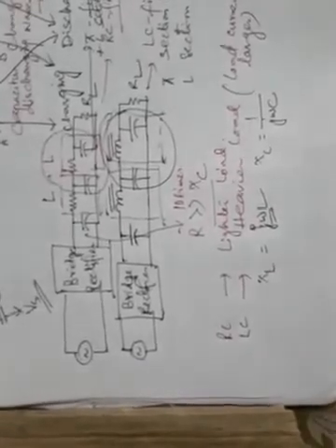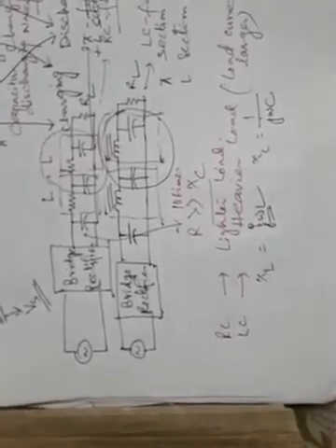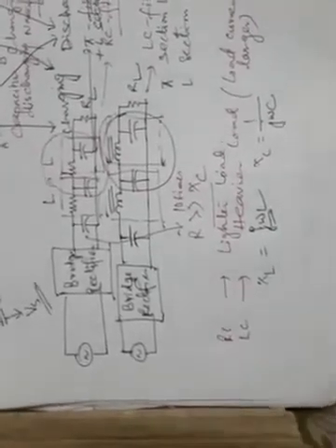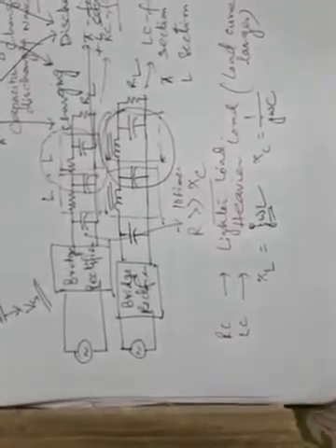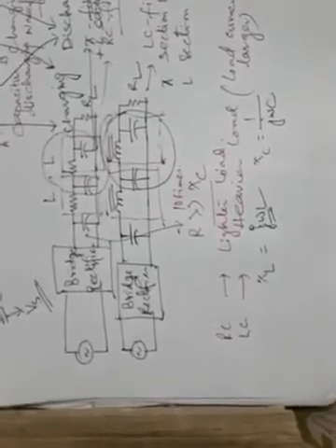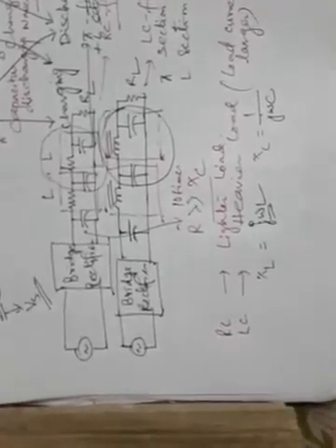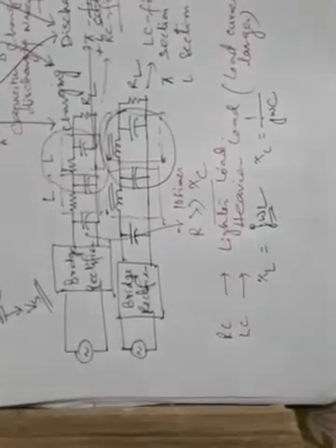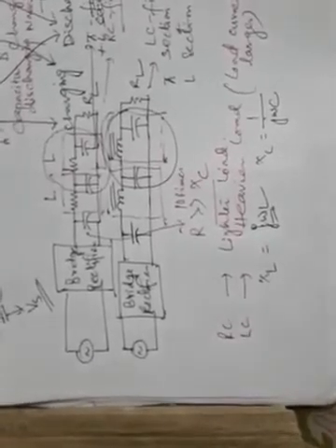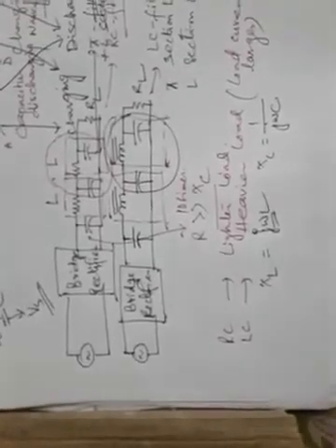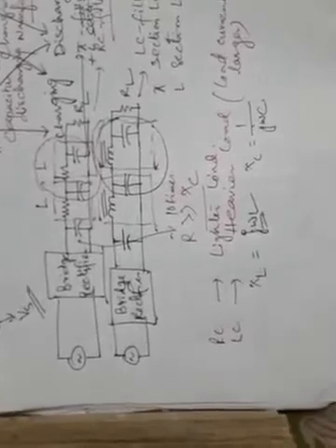So we can in this way reduce the ripple to a very low level, and the DC voltage drop across the inductors is also much smaller than it is across the RC combinations, because inductors are not that much of a lossy component like a resistor, because the winding resistance of the inductors is generally chosen very small. That's why the LC filter is more popular than the RC filtering scheme. But still nowadays the LC filters are becoming obsolete in typical power supply applications because of the size and cost of the inductors, which are generally higher.